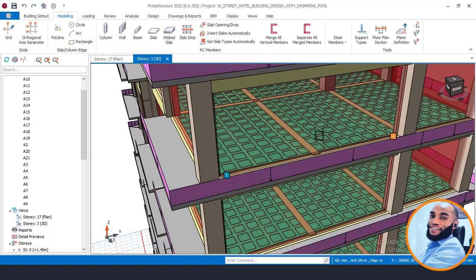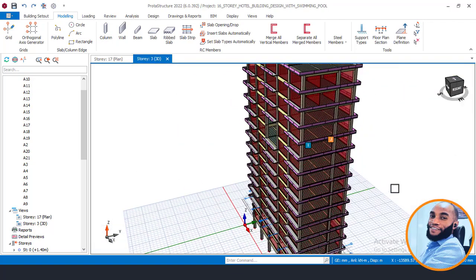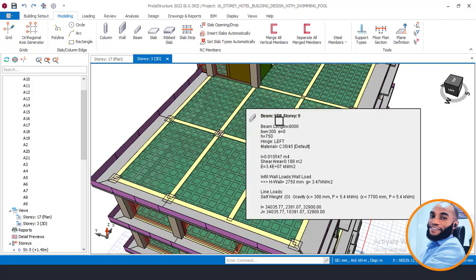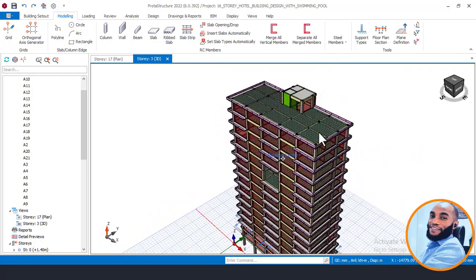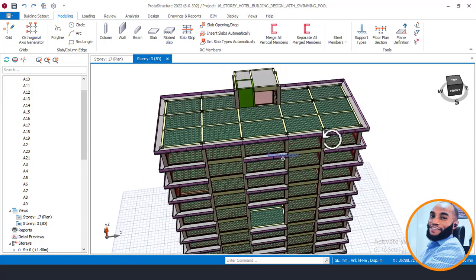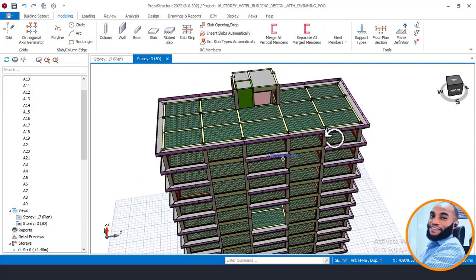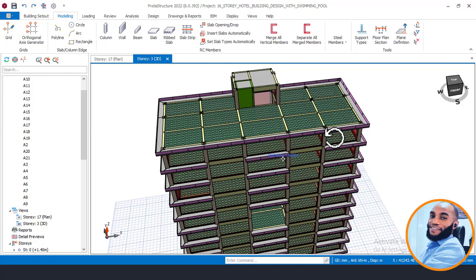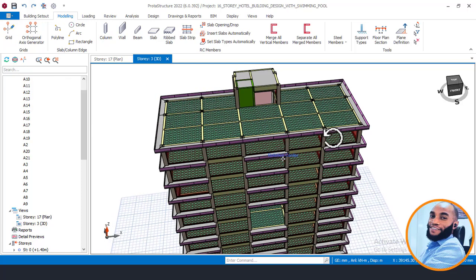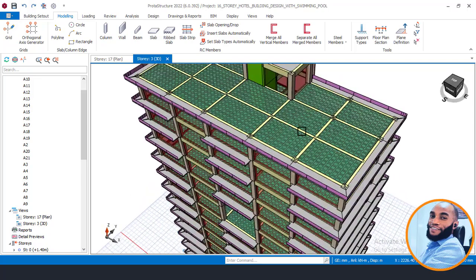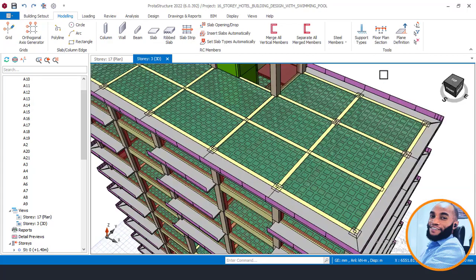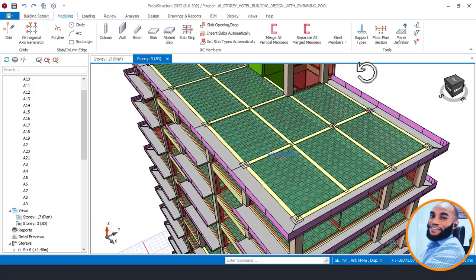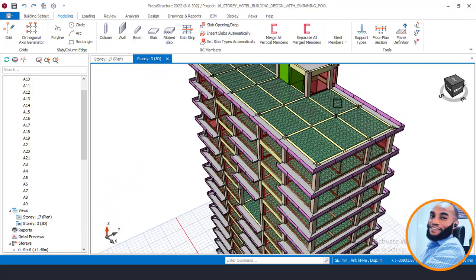Okay, so you can now see how the building is looking very light, because of this waffle slab that we have. It's looking light now compared to when it was just a solid slab. Okay, so on the part 9, I'll be showing you how to reduce the load based on percentage, because we are going to apply those 2 methods of load reduction on this structure. The method based on the type of the slab, which is changing from the solid slab to waffle slab, or what they call ribbed slab, and then also reducing the live load again using percentage based on the story, which I'll show you on the part 9. Okay, so watch out for the next.